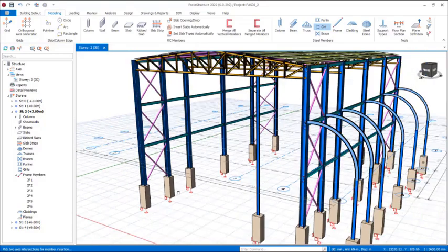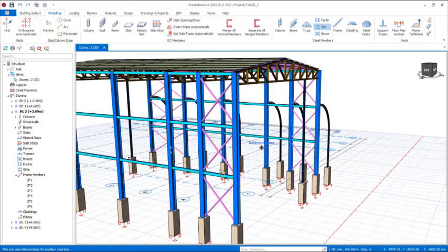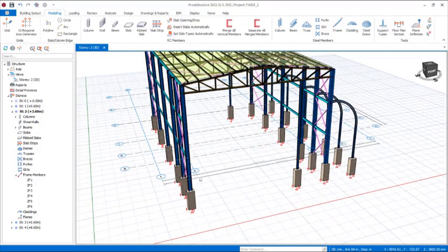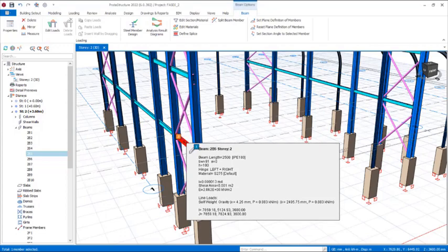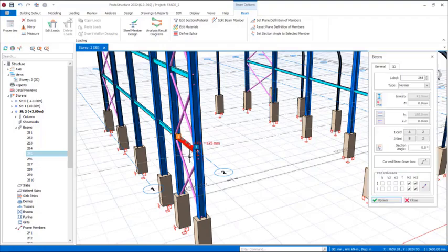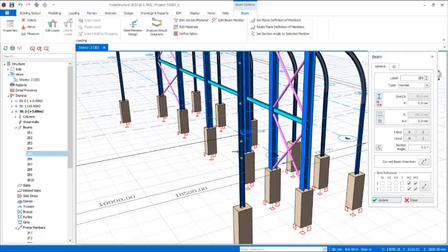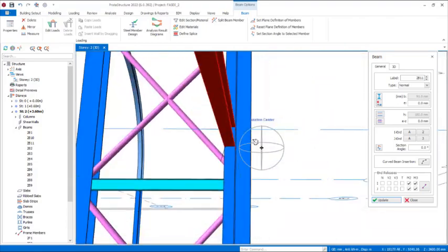But at first, I would like us to have a beam that will connect this column and this column. So for us to do that effectively, you just have to deselect the gate that you have already selected. Okay, so at the level we are, this is level story 2. Okay, so you just select this one. We'll be using this property, the property of this beam. Right click and then click on the property. You can now immediately pick this first point, and then all the way to this point, you pick that to actually get the beams inserted, just like this.